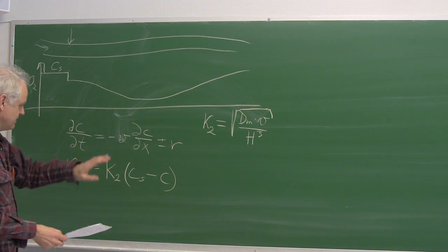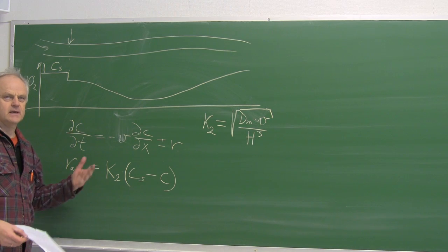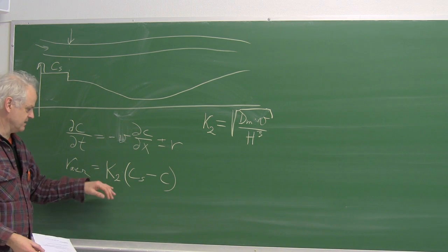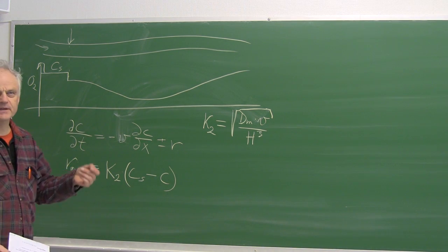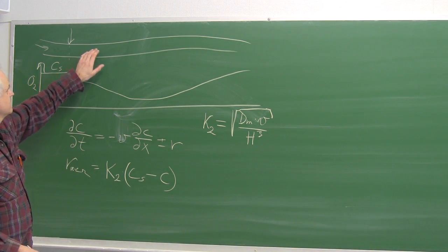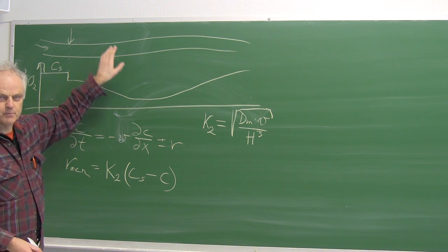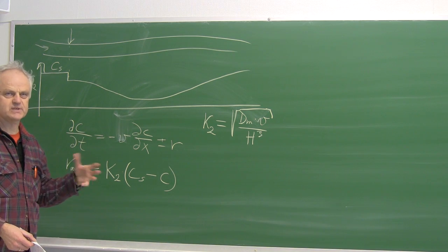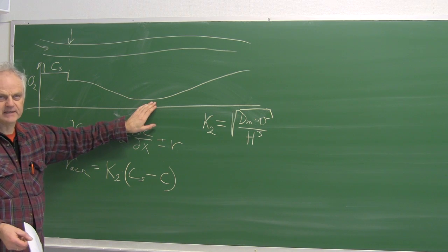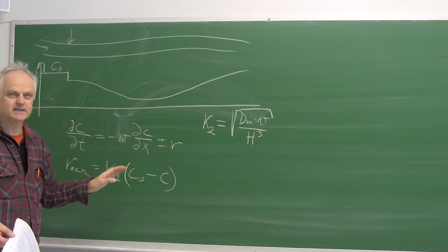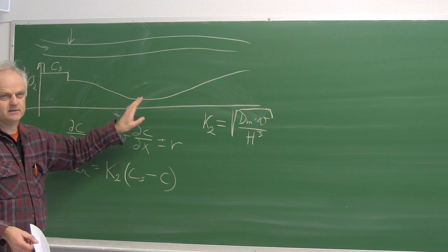It's not so important. The important thing is we have a value that is typical for some river, or in other cases when we aerate something, we do something else. There are also examples from practical life where people put in extra barriers to create more turbulence and more mixing if a river has trouble staying nice and aerobic, because we don't want it to go too low so that fish are dying. That's the main idea here. Keep it always from going anaerobic for sure, but even not close to that.